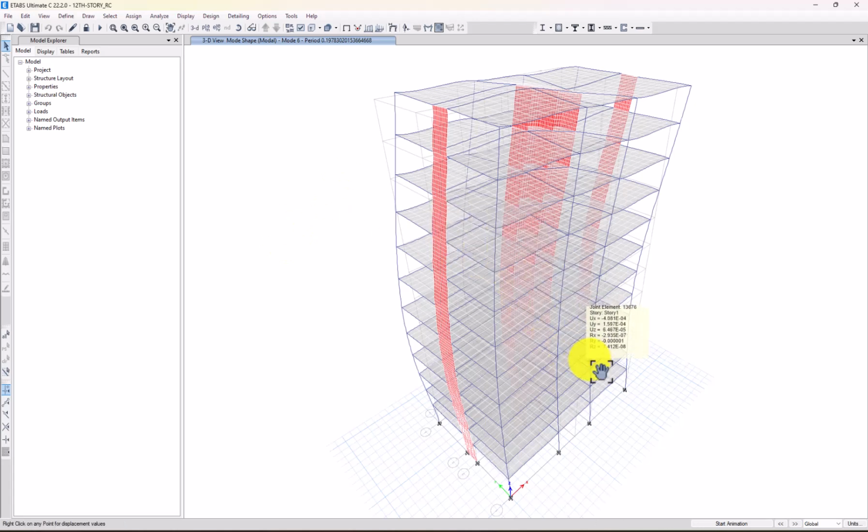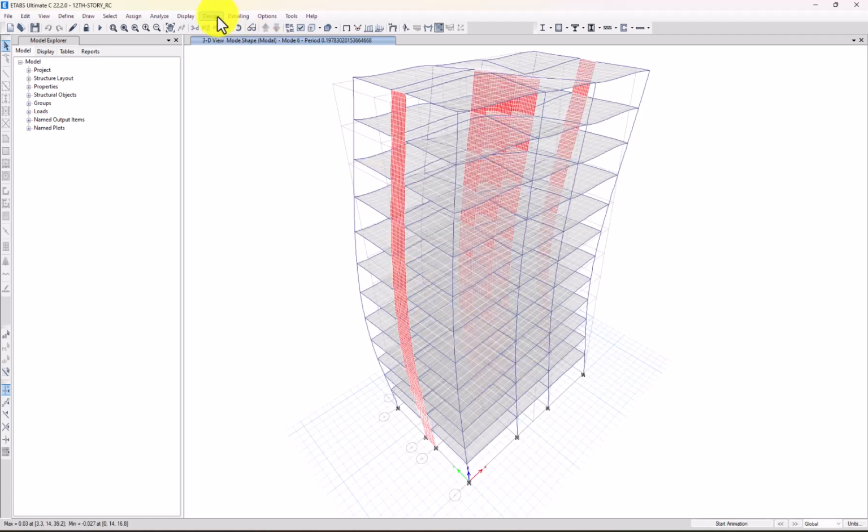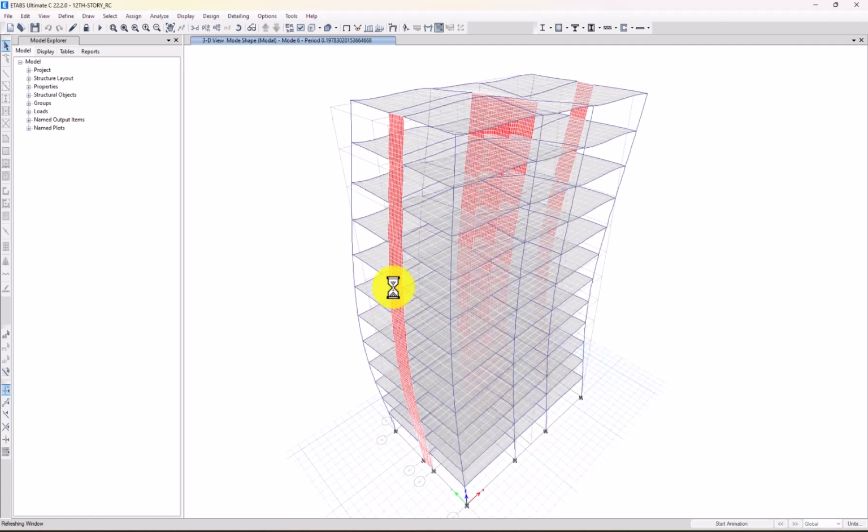For the design of the structure, you can actually take this data, especially the drift and displacement, and then check with the allowable drift ratios. So in my opinion, if I reach with this modeling less than 1%, it's okay for me. But the structure is quite stiff, so we can keep it in the range of 1 to 2%, and that will be okay. Now for the designing of the elements, we can start by designing the beam column firstly.